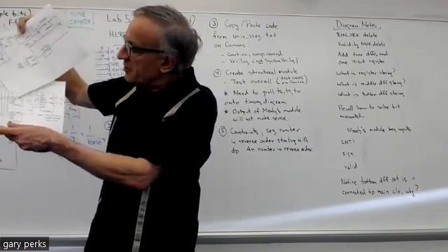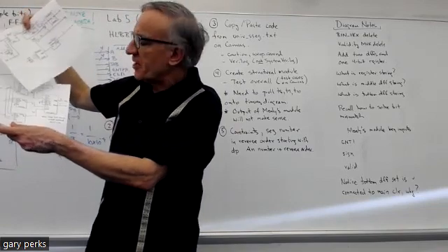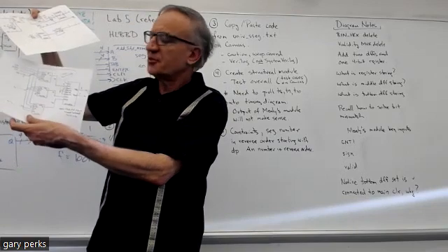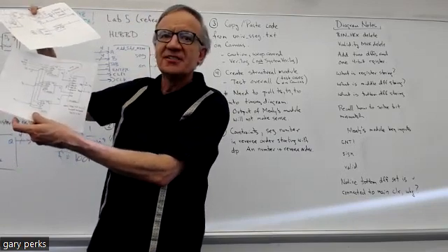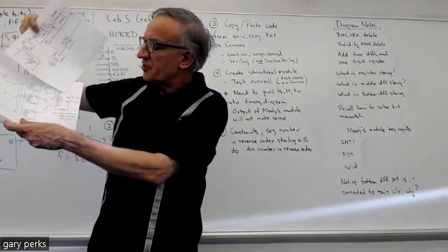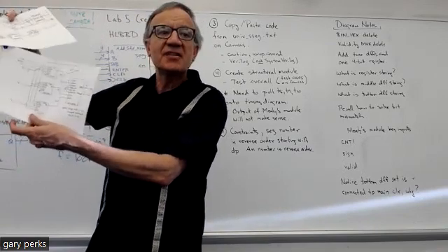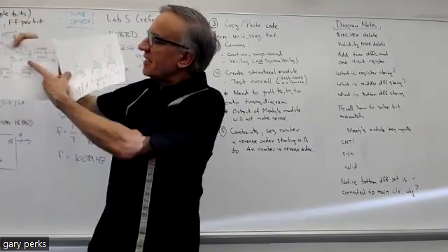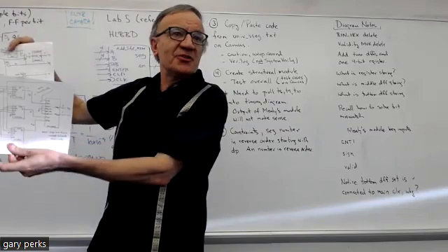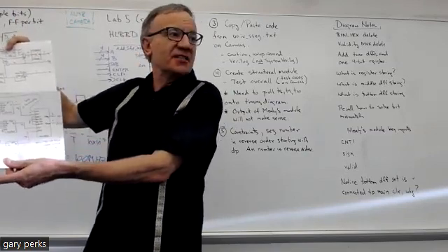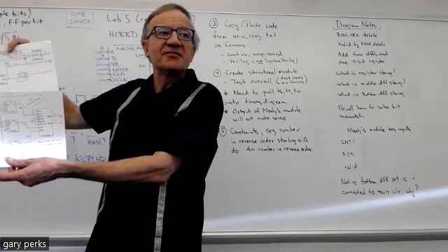How about the middle register, which is really just a flip-flop because it's only storing a single bit? Look at where its Q output goes. The sign bit: it goes to the sign input of Mealy's module. So it's storing whether you have a positive or negative. Look where the D input goes, T6, the output of that AND gate, which identifies whether your result is positive or negative.